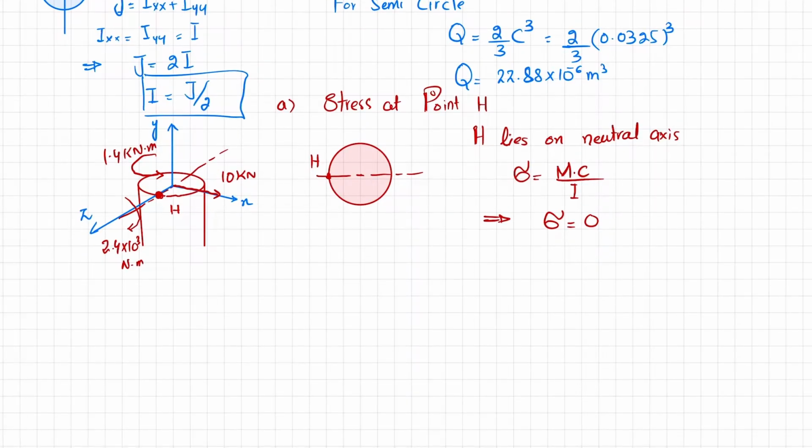Now we have a shear force on this face, so due to shear force there will be a shear stress, and that shear stress is equal to V into Q divided by I into T. V we know is 10 into 10 raised to the power 3.